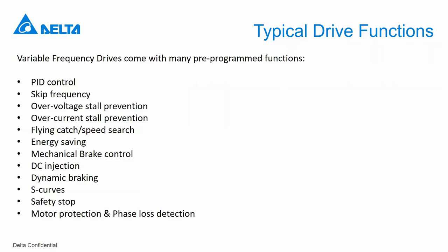There is one question still about that ramp direction. The question was, if I want a pressure of 6 bar, if below it ramps up and if above it ramps down, can I change it and operate it in another way? But normally, automatically with a PID and a pressure sensor, it will always go up and down around the 6 bar that you have as set point. Yeah, that's true. I don't quite understand the statement, can I change it and operate it the other way? Definitely you don't want to run it in reverse, I'm sure of that.